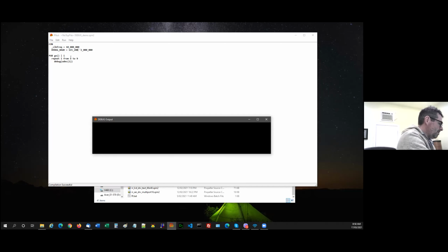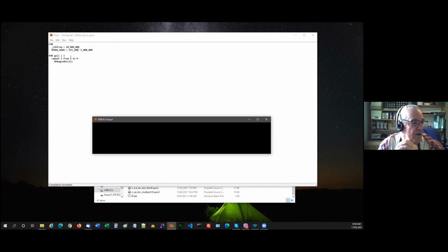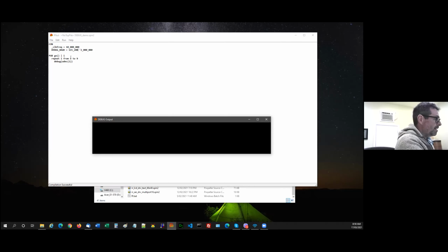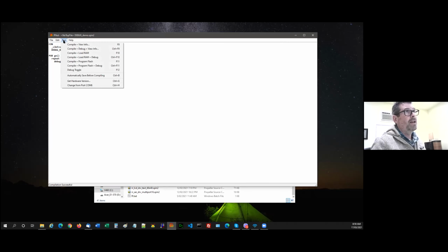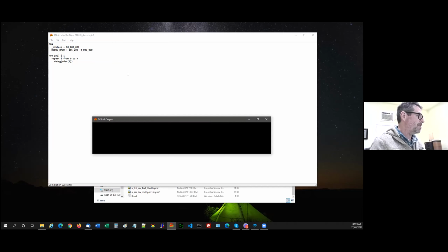And I don't. Well, I just tried 115200, and I would expect 115200 to work totally on the FTDI chip, and it does not work. Well, I think what's happened is the FTDI chips have some kind of non-volatile memory in them. And I know that we configured them through some sort of application for the P2 eval board. I don't know that we did that for the prop plug, but there's some kind of settings difference between the two.